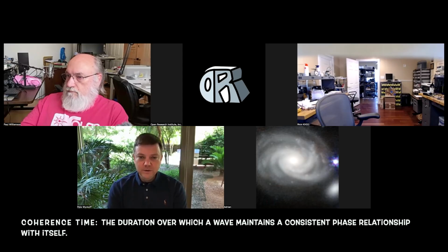So one of the simple examples of that is VHF picket fencing, when you have a mobile channel with maybe two different multipaths. It turns out the only reason it picket fences is because we're sending a CW. There are other waveforms for two-path time-variant channels that have much longer coherence time, where there aren't fades, but you can't just use an FM modulated CW.